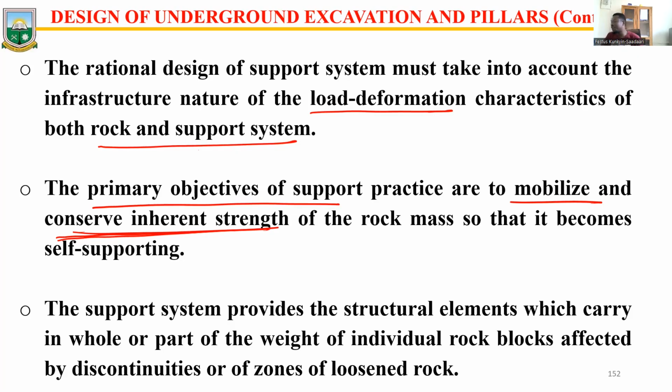So the support system provides the structural elements which carry the whole part or the weight of the individual blocks affected by discontinuities or of zones of loosened rock. If I'm bringing in support, there are two things. The support system is either to support a section of a block, or the whole block, or certain places that have discontinuities which I want to provide support for.